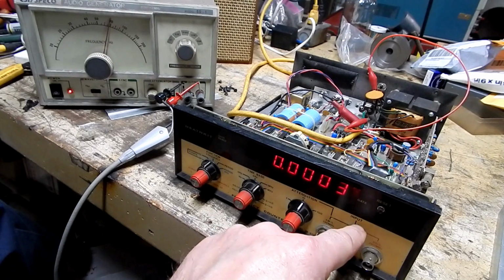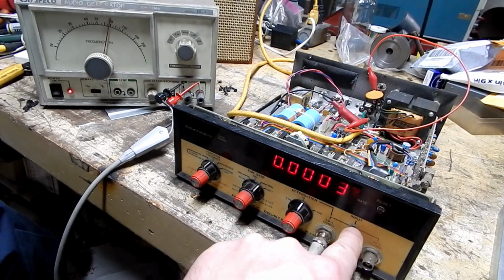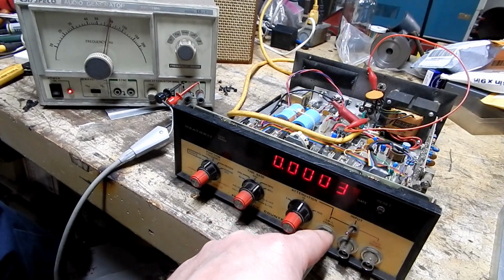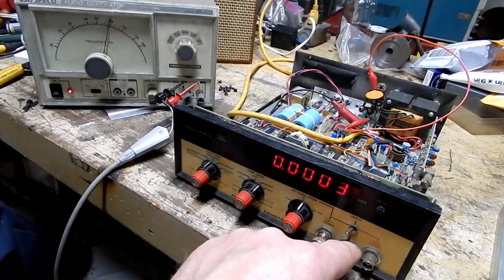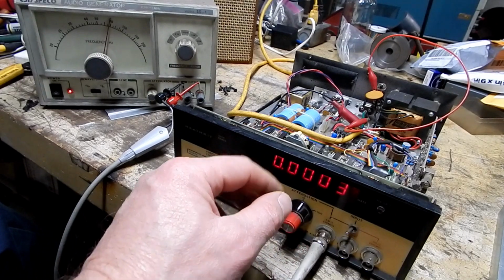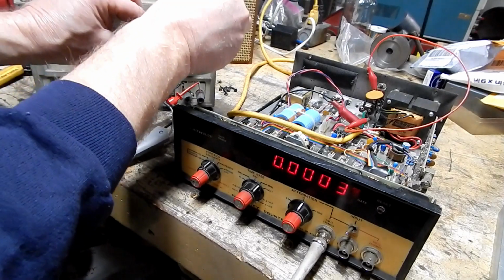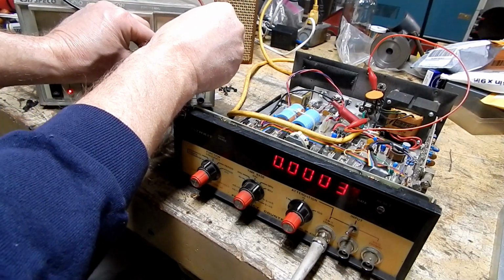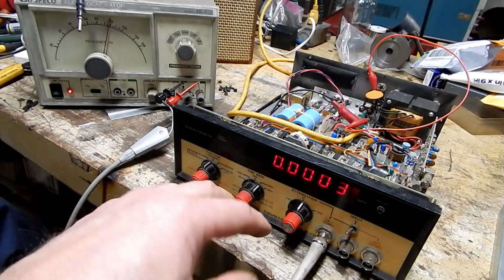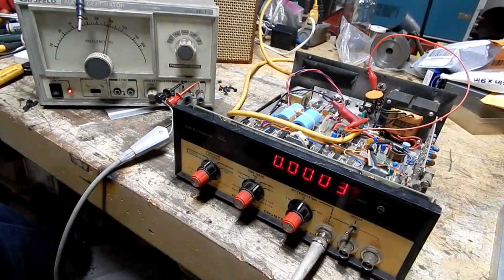This input switch appears to be to select which one of these 3 B and C inputs you're using. So I've got this in the correct position. And I've even tried using the other inputs and seeing whether or not there was any action through those, and they all seem to be dead. So I'm pretty confident that the frequency counter is the issue. I even double checked this to make sure. I still have signal coming out of the generator, and this thing's just doing nothing. So I think this is a sick frequency counter.